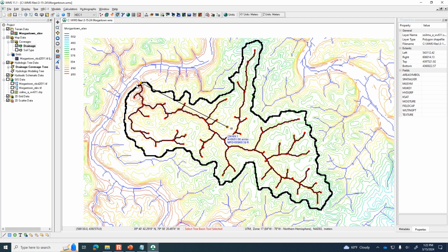So when we dropped the outlet, when we put the little dot on that flow accumulation cell, it's asking the question, what are all of the connected cells where water flows to that location? So any raindrop that falls in this boundary is headed towards our outlet, just by virtue of connected elevations.